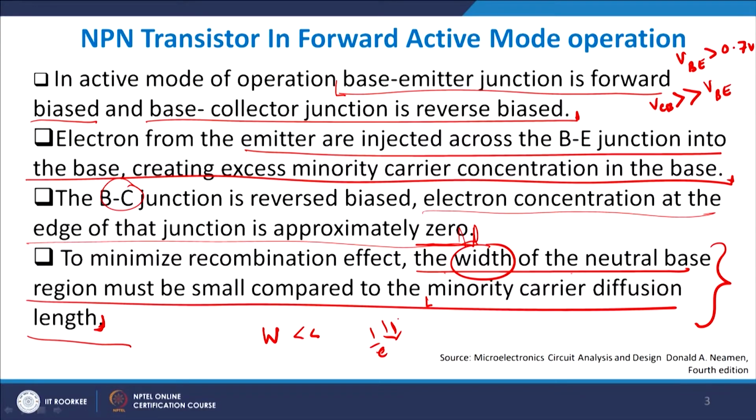So, if you entered at this stage and went to a distance of 1 centimeter and saw a drop in the number of charge carriers by virtue of recombination, and 1/e of the charge has actually fallen, then we define that length to be the diffusion length. So, if your base width is even smaller than that, then by the time the electron starts moving, I would expect to see that no large recombination has taken place.